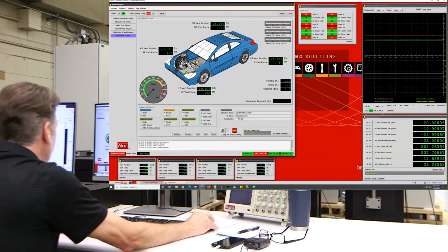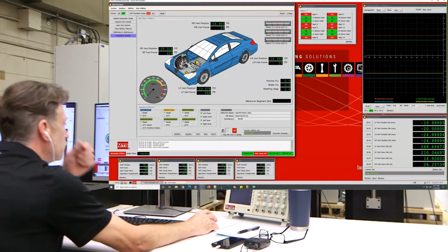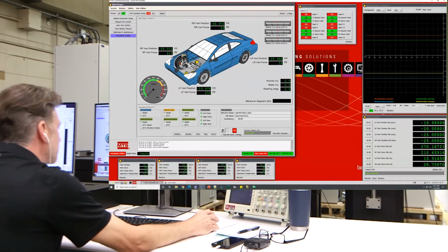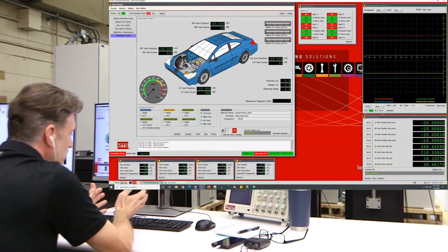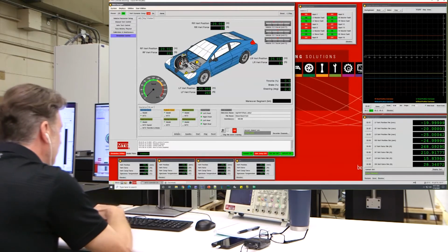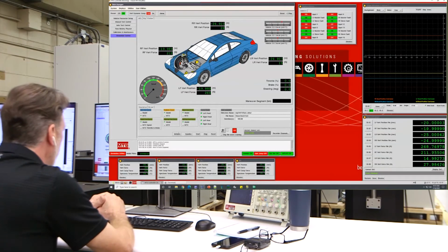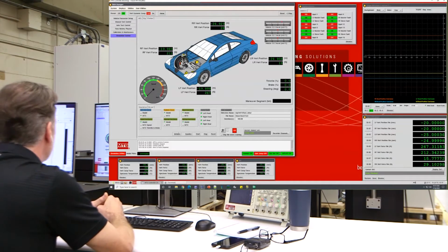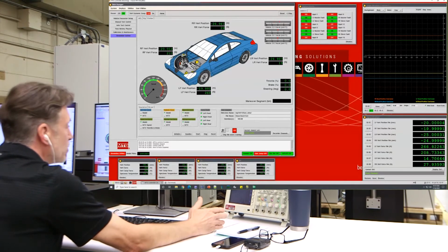On the bottom here, I've got buttons that represent that sequence. So to start out the process of putting it in the loop, the first thing we're going to do is initialize or start that simulation. And as Juan had demonstrated, this is the same simulation start that you would do normally offline with any of your vehicle models. Typically it picks the vehicle up virtually in the air, drops it, and the suspension and system will settle in at a ride height based on the laden condition of the vehicle. But typically the simulation will start at that point.